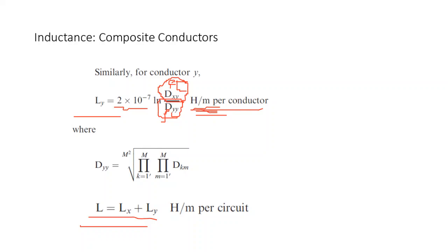So we have 2 conductors, X and Y. And also we have inductance between them. These are only because it is single phase, by the way. If we have 3 phase, then we need to calculate the inductance. And that's what engineers do. You need to calculate the inductance beforehand. Okay, that is offline. And then you put it on the software, or on the system where you calculate the load flow.